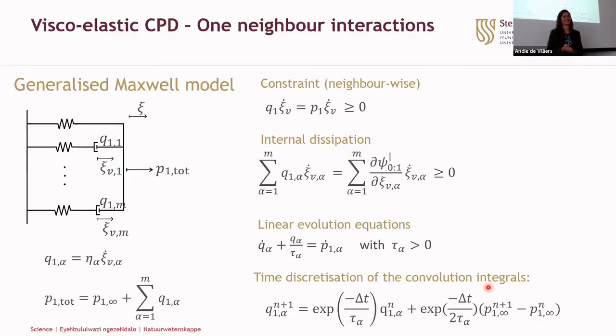You mentioned earlier the elasticity, there was an inequality side, and then we moved to viscoelasticity with equality. The other way around. So in elasticity, there's no dissipation. So the energy is not lost through heat and things like that. If you take an elastic material and you do anything with it and you take away the forces, it will go back to its original shape. With viscoelasticity, this is different. It will go back to a new equilibrium, but not immediately. It has this history dependence. The viscous part.